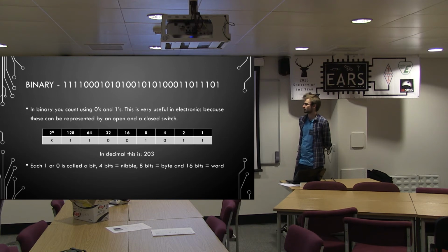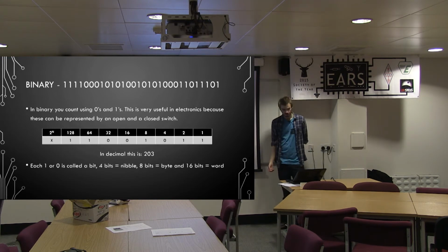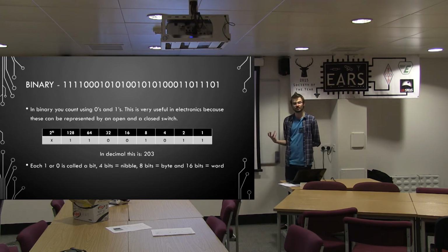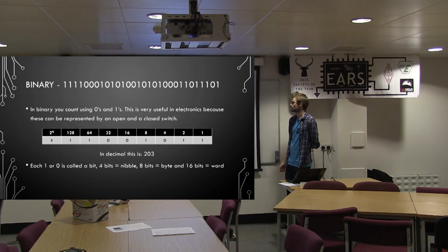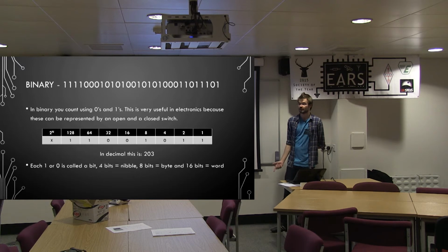This is how it works actually inside the microcontroller, and when you're transmitting through serial, it will transmit 1 bit at a time. Generally, most of this is all wrapped up in the microcontroller for you, so you don't have to worry about it, but there will be certain applications, like the shift registers we'll be looking at next week, where you will actually be looking at the individual bits for what you need to do.